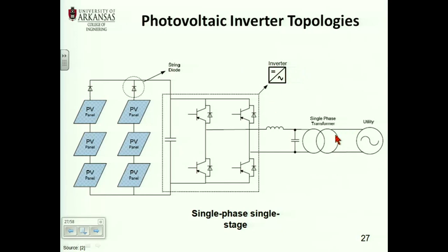This is the inverter, and here you have a single phase transformer if you want to step up. And this inductor and this capacitor here, this is a DC capacitor, this is an AC capacitor, and this is the output filter, because here the output is a PWM signal, the utility is sinusoidal, they are not equal, right? So someone has to take the difference. Now, when you have a single-phase transformer, you also have the leakage inductance of the transformer.